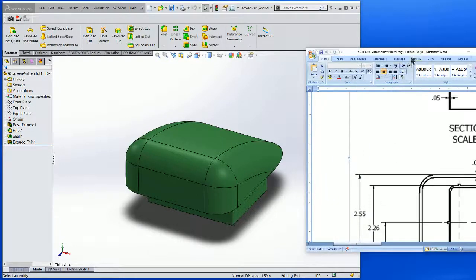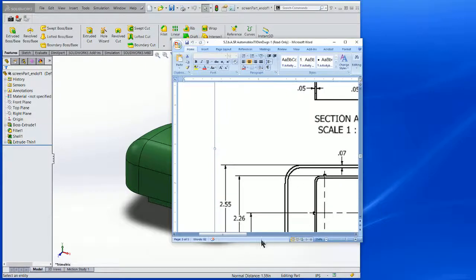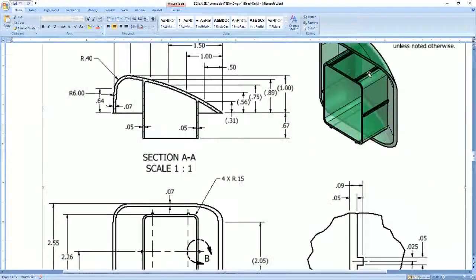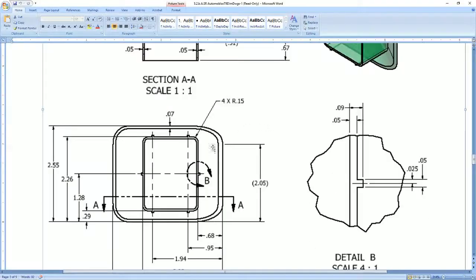So real quick, what we're going to do is add in these little plastic extrusions, or little plastic ridges, on our model. You're going to see that they're symmetric about a couple different planes. This happens to be our right plane when we built it, but we don't have anything that goes down the middle of the model. And we want to get that symmetry so we can use a mirror feature.